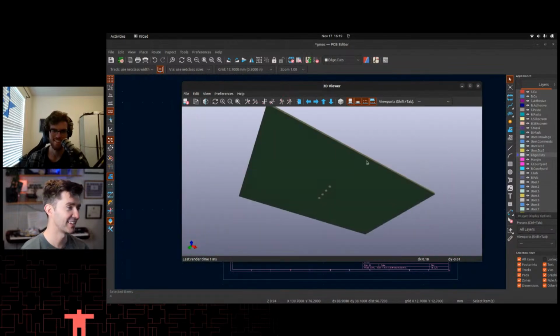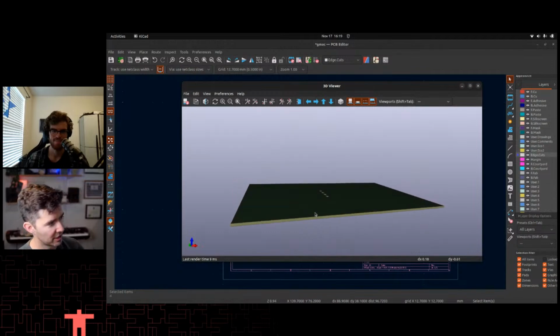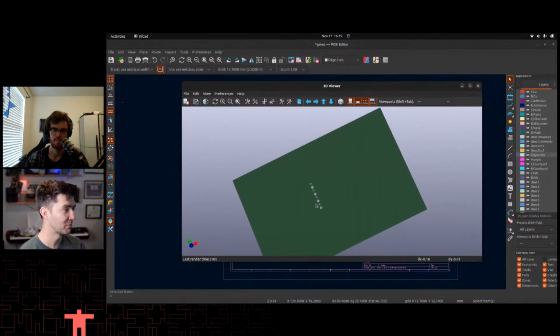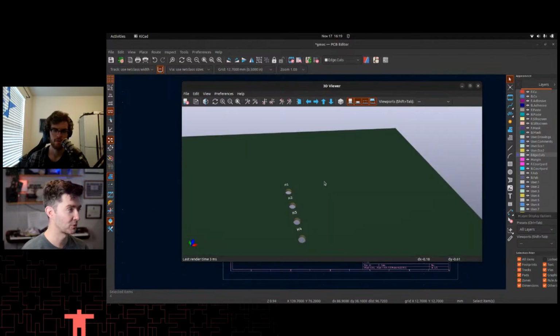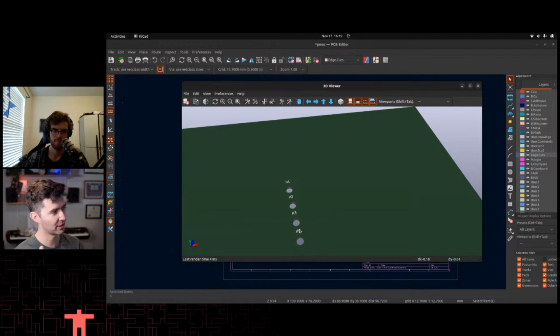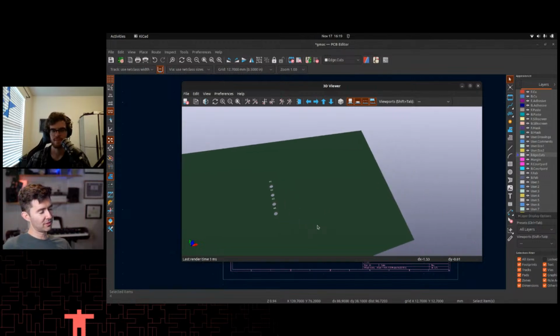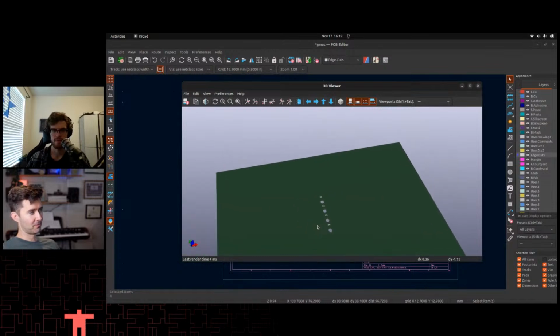I mean, there's actually some limitations. Some board houses, I don't think a lot of the Chinese ones that I use, will actually limit this, because when you're making a circuit board, it's literally a drill going through a board, right? So if you had super high density, if you just did vias all the way across, which are basically drills that they then backplate with copper, it's a really expensive process for them, and it really adds up. So for a high via count board, some manufacturers will say that's too high, or we're going to charge you more. So yeah.